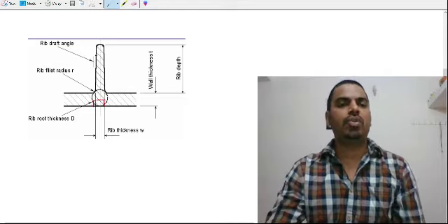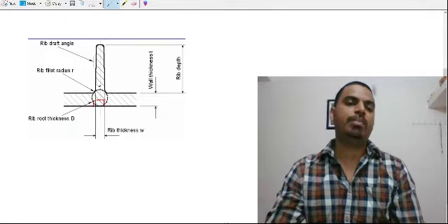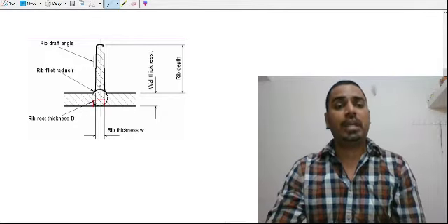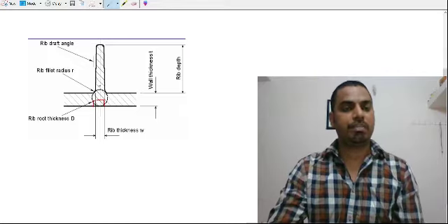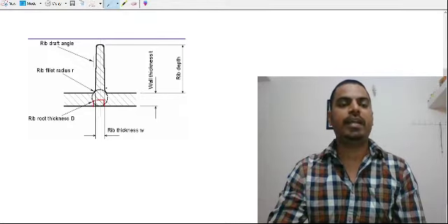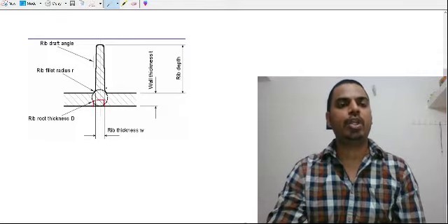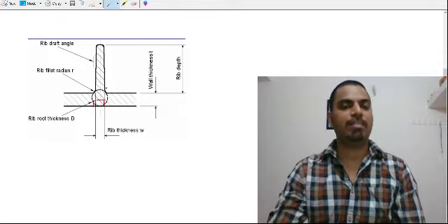It will also cause a filling problem for the plastic melt in that gap, and also a machining problem. Also, due to the increase in injection pressure, the rib surface might get gripped to the cavity surface. So we cannot use a thin cross section rib.